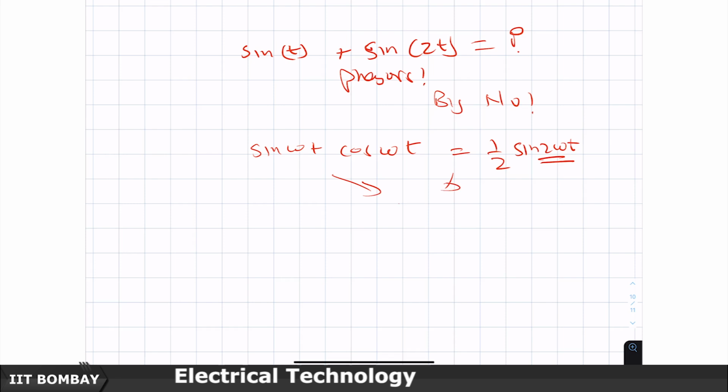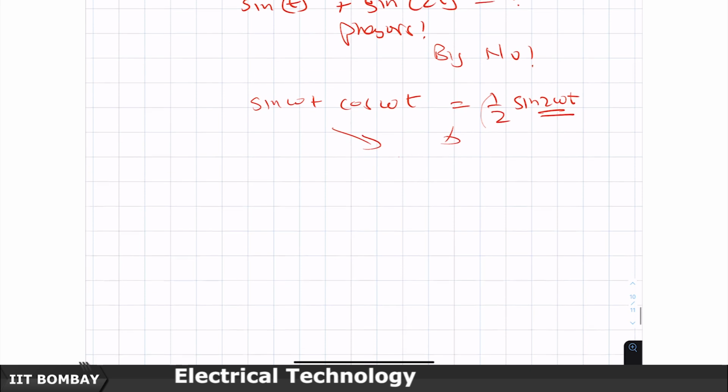imply a phasor analysis. It is only with addition or subtraction that we can directly use vector algebra. Multiplying two phasors at the same frequency will not create a new phasor at the same frequency. This is something altogether different, the frequency has changed to 2 omega. So, please be very careful about phasor analysis. It can be done only in manipulating, that is adding and subtracting, sinusoids at the same frequency, but even with such a limited ability, a significant amount of electrical engineering gets done.